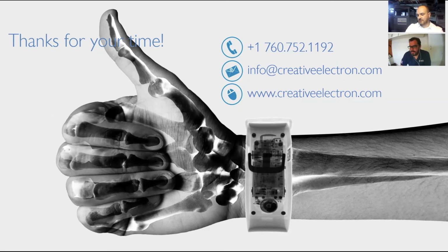And then of course you get the location in Z. You have to do a 2.5D or a 3D inspection to figure out if the void is close to the board, close to the component, or right in the middle of the ball, which would be a different story.